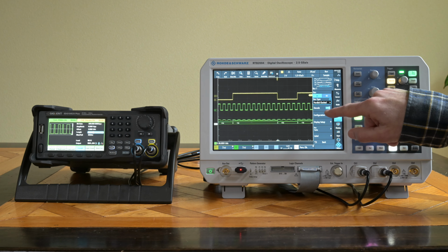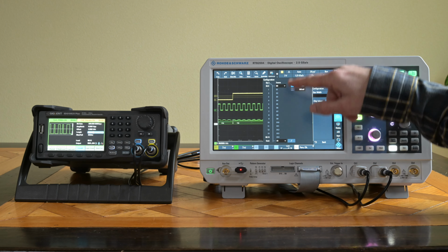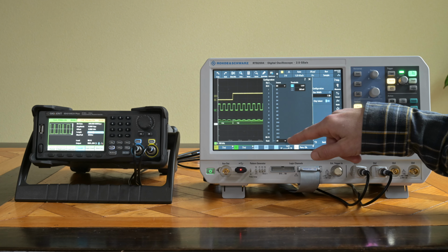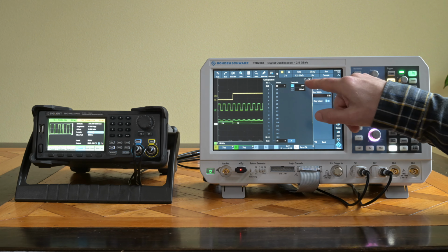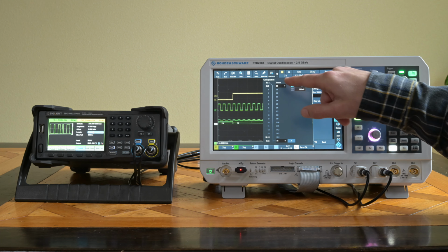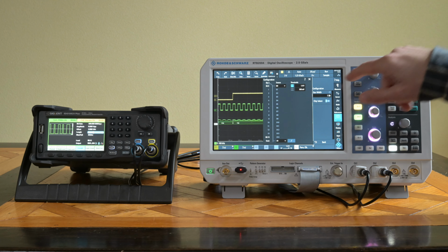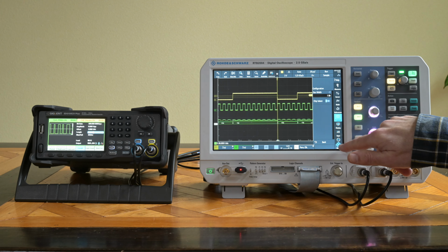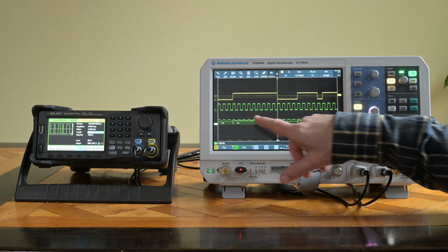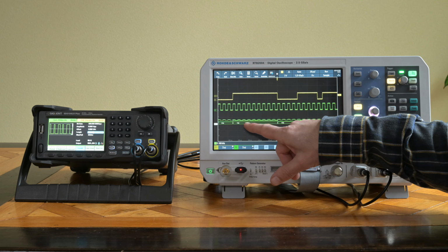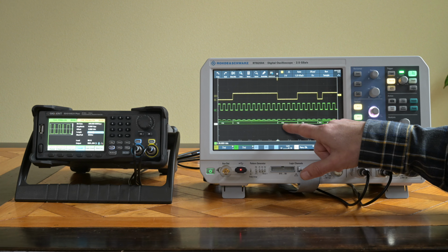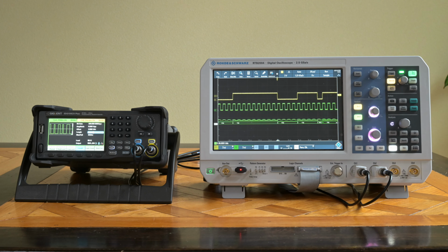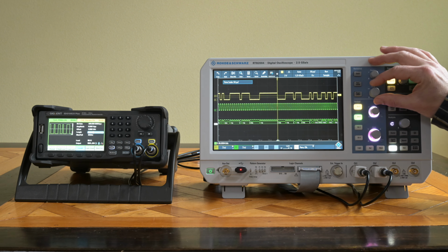Let's go and see. We need to configure this parallel interface, so normally you might configure 8 or 16 bits, or 15 bits in the case that you also need a clock. Actually, I wrote some comments on that in the compare document, but that's not the topic of today. I can set the right thresholds. Now, I took care of all of that. So we're going to decode a bus with just one single bit here. And if we go back here, we see it's already kind of doing that. So we see here, these are all ones, and then as bits, not hex or whatever. Here's the 0. Here we see 1, here we see 0, exactly corresponding to the values here.